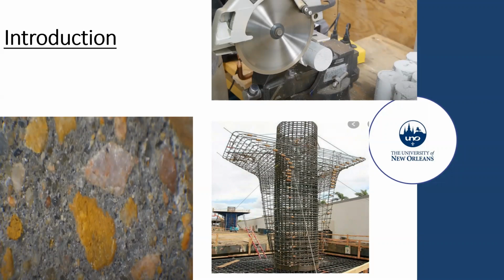Also, adding water increases the workability, but the workability comes at a cost to the concrete strength. Like I said at the beginning, if you add more water, you will increase the workability, and your concrete mixture is going to flow without any problems into the formwork. If you look at the lower right corner, this bridge pier, it will be hard to place concrete if the workability of concrete is not enough.